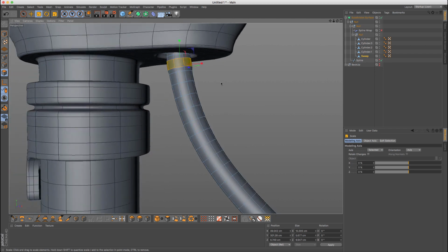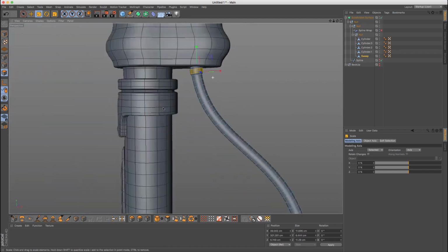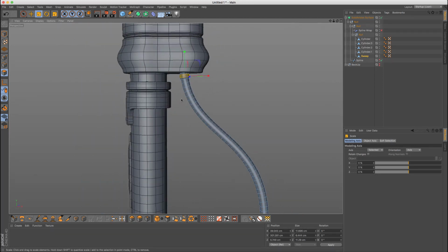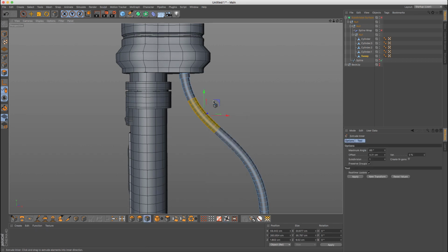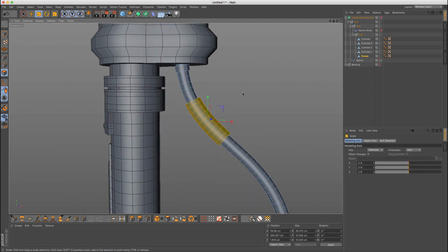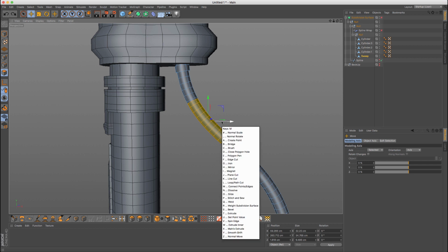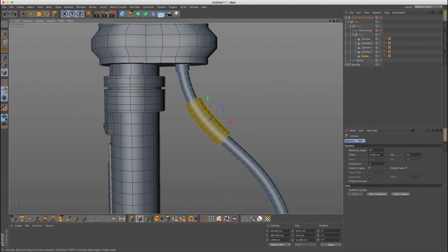So when it subdivides, I have kind of this small transition in this area, and we can do it maybe a few more times here. So let's do extrude inner, and also maybe we can do extrude outwards. And now we cannot scale as we could have before, simply because you will notice it will go in a different direction. So if you do that, you'll need to make sure that you reposition. And as an alternative, what you can do is do extrusion like that.